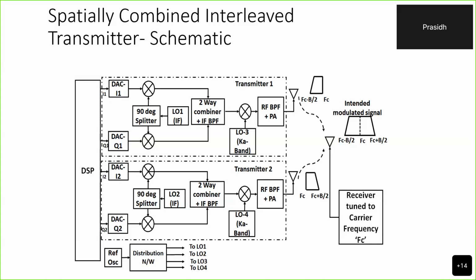Which means the higher the number of subcarriers, the greater the peak power. Now, the greater the peak power, the greater the linearity needed from the RF power amplifiers, which is basically a circuit designer's headache, to maintain both linearity and efficiency. So by cutting down the number of subcarriers to half or a similar fraction, one reduces the peak power. Then for the same input power, the amplification one gets is at a higher efficiency. There is a study of this in one of the upcoming slides.